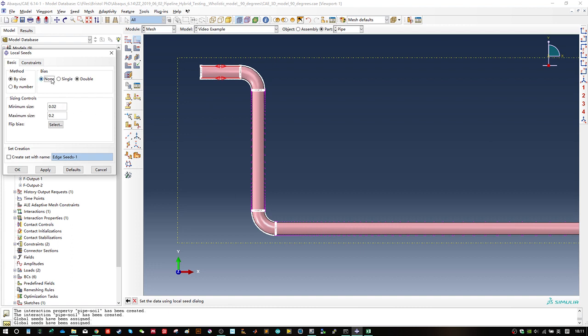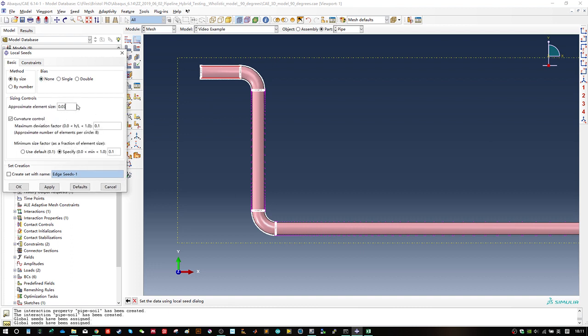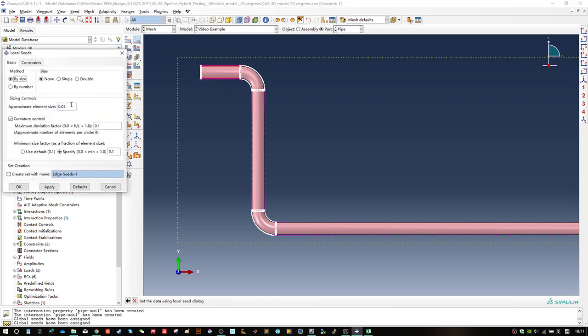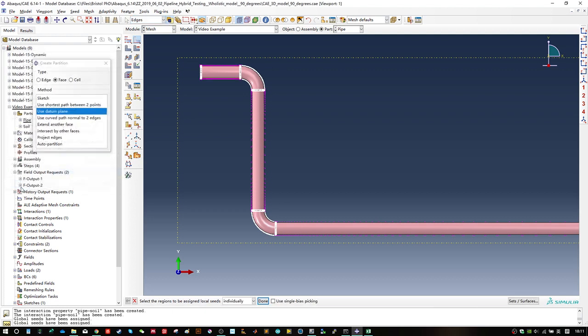Finally, since I'm not actually gonna run it, I can go crazy here and put everything in very small number. But for you, if you're gonna run it, you're gonna have to try to run a validation test to see what kind of mesh is appropriate to give you a very reasonable analysis result, and at the same time without costing you too much time. So that's done.